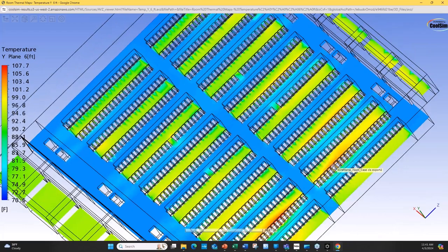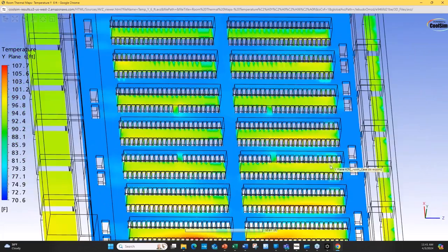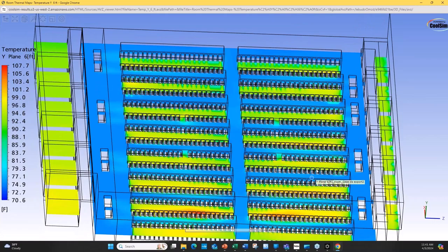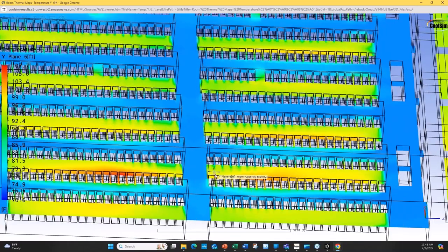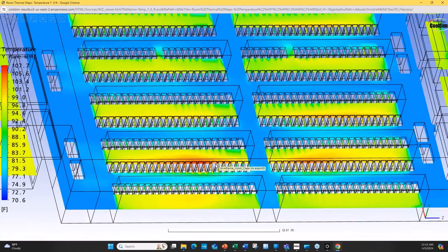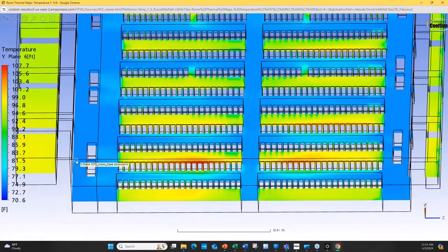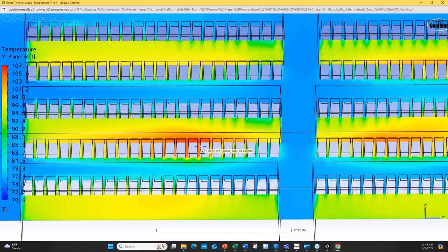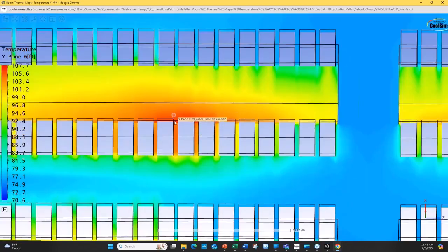Exactly correct. Unless you have proper sealing on these designs, and these designs are critical. And by the way, this will happen also in other cases where you get a pressure differential. For example, if you have the chillers go down or fans go down on the air handlers, you'll get a pressure differential and it'll come leaking through. And the leakage often occurs here.